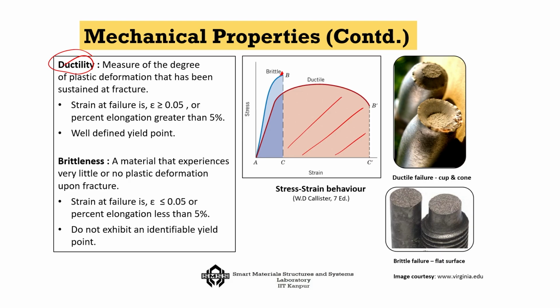As I told you, how far you can go for a material in terms of the yield strength is the level of the brittleness of a material, because some materials show that the failure strain is very, very low. Okay, you cannot really take it like a ductile material.